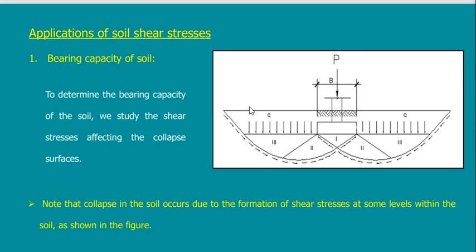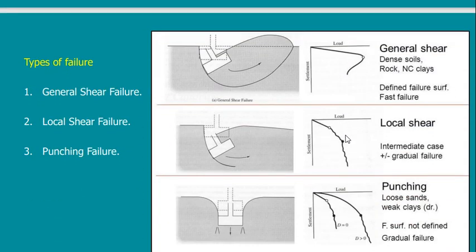We took all of this, and we said that this is the normal shape of failure for any footing. Usually, if my footing is going to fail, then this is how I expect it to fail. The foundation will push this triangle below, and this triangle below will push these wedges at the sides, and these wedges at the side will push anything next to it up. So this is the normal shape of what I expect to be the failure of the soil.